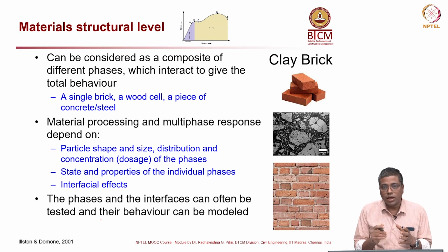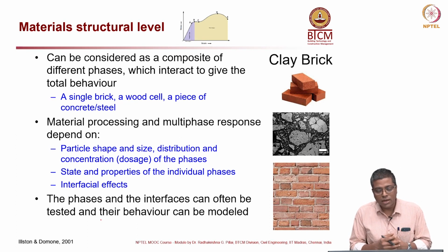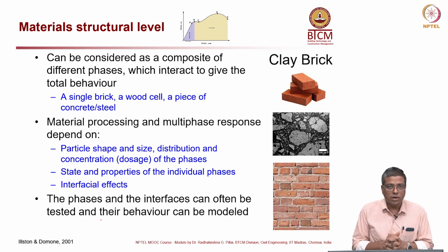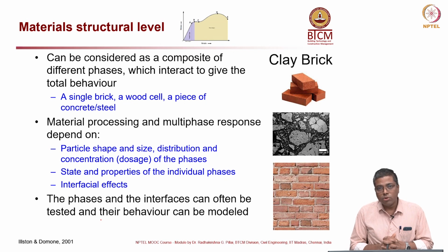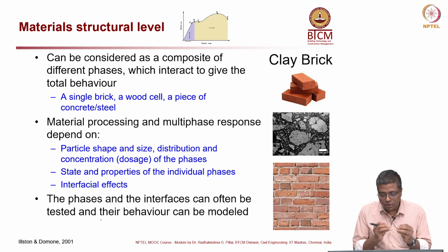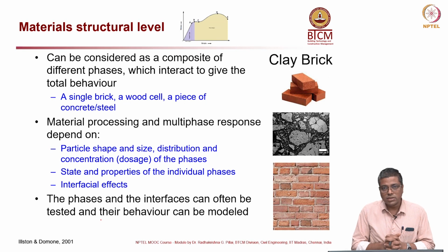And of course, clay made in one place may not be the same as in another place, and if you don't heat it properly, you will not get the properties you desire. So a lot of chemical reactions are involved in the making of a brick, and if we know the type of clay materials used and the type of processing, like the heating treatment, then how the various phases or material elements within the clay system react, behave, and how well they are bonded together can tell us what the strength of the brick could be, and whether it will behave in a very brittle manner.